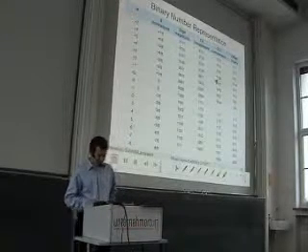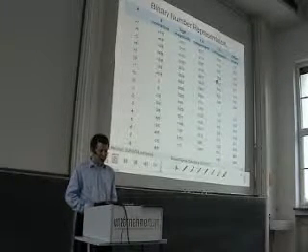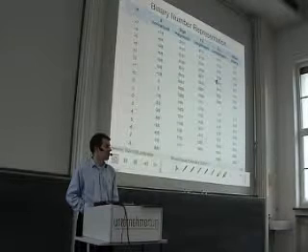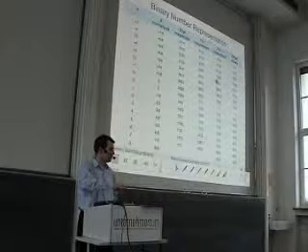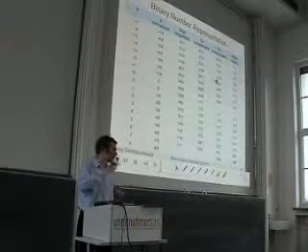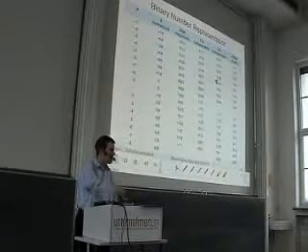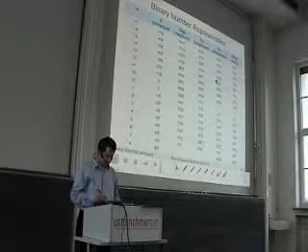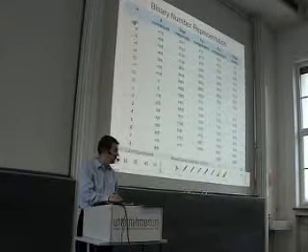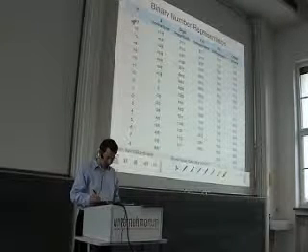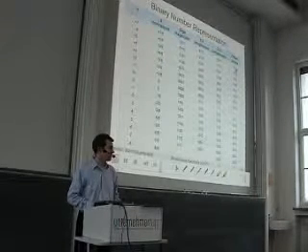Another number system that is quite common in mixed signal systems is the offset binary. In the offset binary, we start from the lowest value that can occur, so usually the largest negative value, as a negative value with the largest absolute value. So from the smallest value, and we count up until the highest value. In this example, our lowest value is -8, the largest one is +7, and we start counting in a binary way from 0 0 0 0, 0 0 0 1, and so on until we end up with the max value.